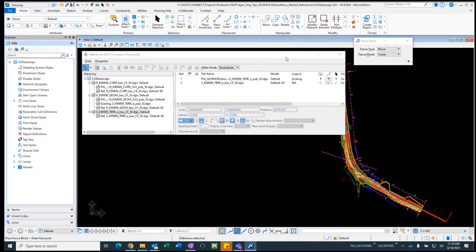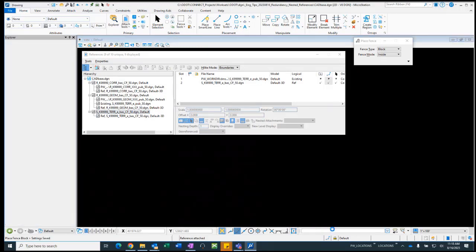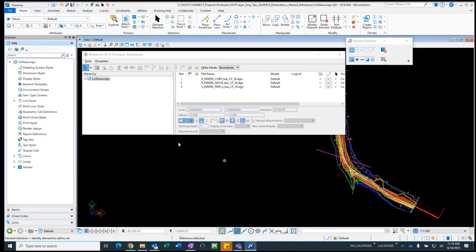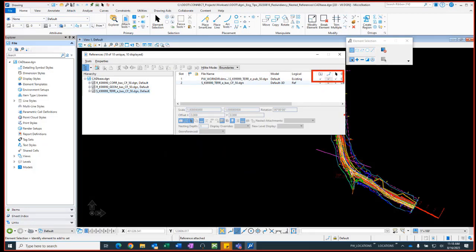So it looks like this is a case where I would need to reopen the file in order to remove the ditto mark and give the control back. So let's do that. I'm going to use the new file command, NE, hit enter, and it's going to reopen the file. And I will select that geometry. I see the pub file is still attached. I'm going to select the terrain container file, and you might notice no more ditto marks.